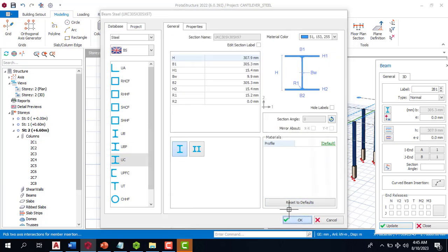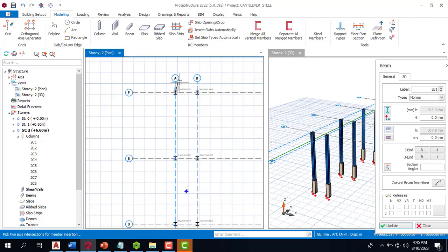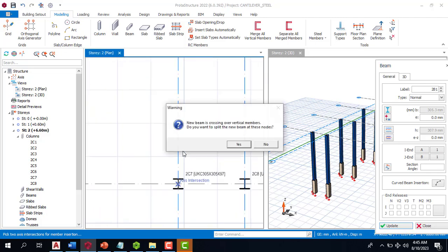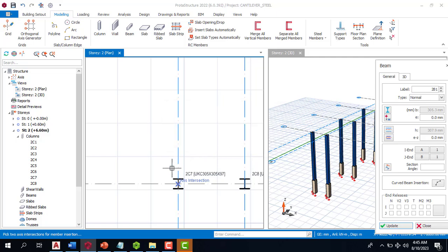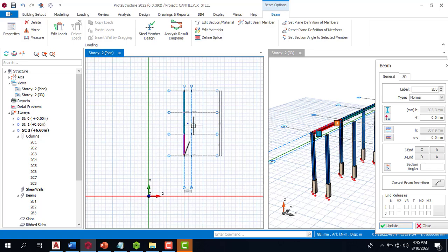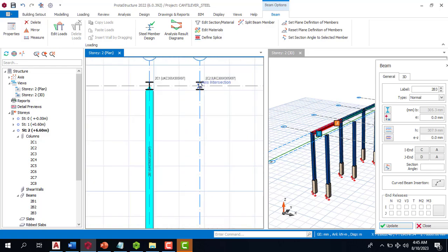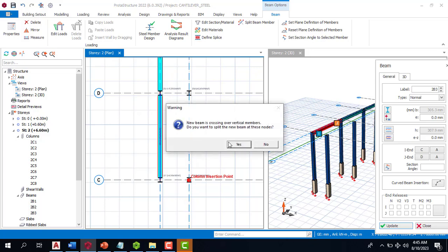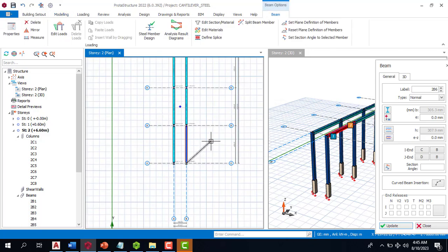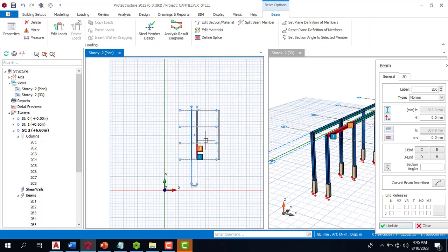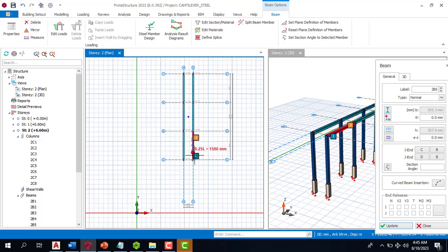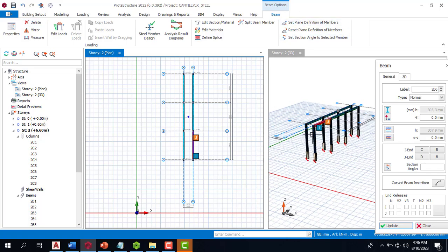But if you don't, you can follow this pattern, and then while the analysis is completed, from there you can simply know if that steel member is economical or is too high. Then you can change the steel cross sections. You can either increase or reduce them by the results the software is generating for you.